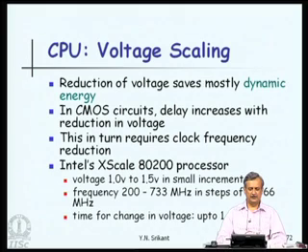So, we definitely will be forced to reduce the clock frequency if we reduce the voltage. This in turn leads to performance degradation. So, the challenge in voltage scaling would be to retain the same level of performance, but with reduced energy consumption.